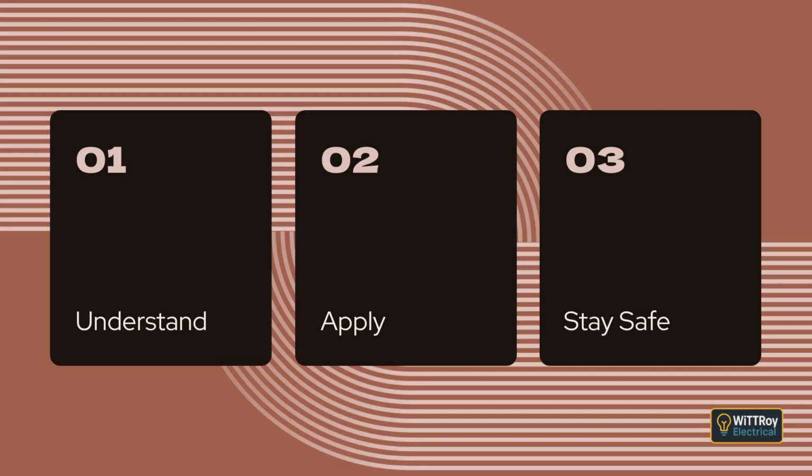Wiring enclosures must be installed to prevent water entering equipment or the enclosure. Where exposed to the weather, they must include suitable protection to stop rain entering. The installer must consider the height of each end of the enclosure, because the lower end may be more likely to allow water entry. Clause 3.10.3 Installation of wiring enclosures.